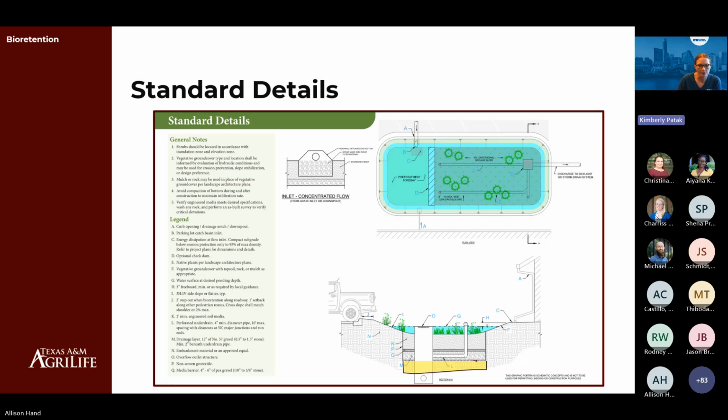And then depending on your site's infiltration, you'll want to do your infiltration testing of the subgrade material. So highlighted here in yellow at the bottom, that would just be your in situ material where you would want to do your infiltration testing. In the implementation guide, we provided a link to how to perform that infiltration testing. So it's important to follow that based on the size of your site, on how many test holes you need. But like we've already mentioned, if doing that testing during the design, but also when we get to post-construction, either do testing formally, or you're going to need to fill your cell and monitor the drawdown rate to make sure that drawdown time is met.